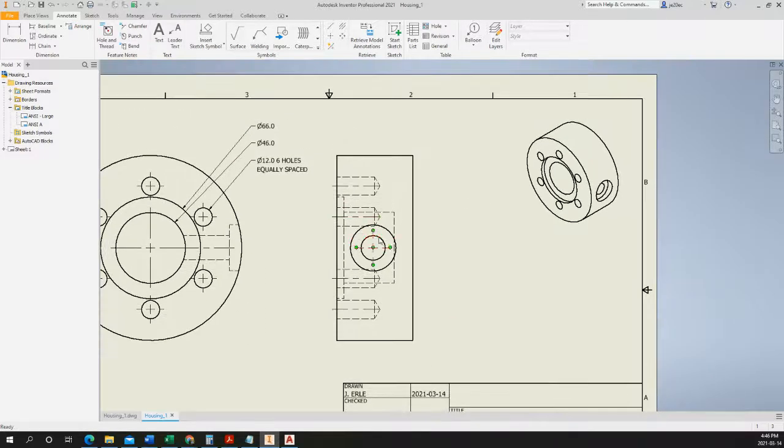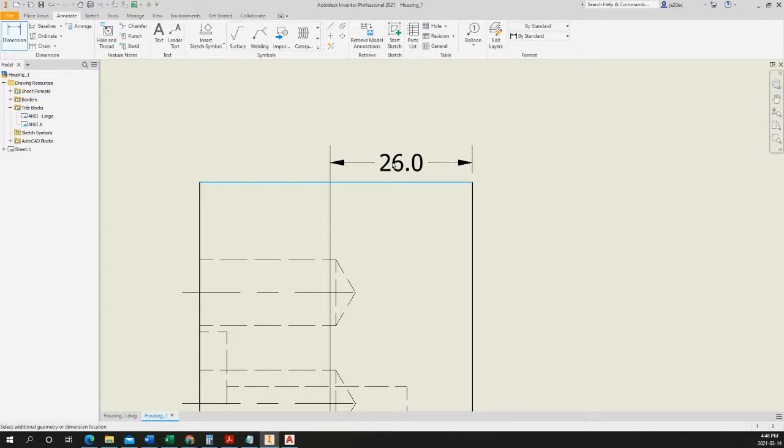Over here, we can show the location of our sidebore, as well as the height of this part. So I just do that quickly. Again, you're using dimension, and we'll come from this line to our center mark. If I zoom in here, I want to show you how these dimensions snap into position. You'll notice as I drag this up and down that it becomes dashed in certain locations. So these are standard distances from the object that we're dimensioning, and that's what we should snap to.